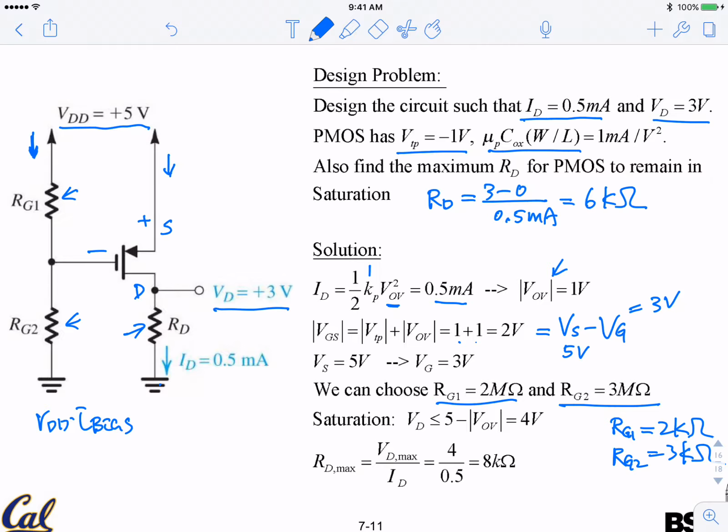This current that flows through the active transistor, unfortunately, you cannot save on that. Your gain is related to your current. So if you need a certain gain, you just need to bias your transistor very hard. You cannot do anything about that. But the bias branch, you can. So mega ohm is better.